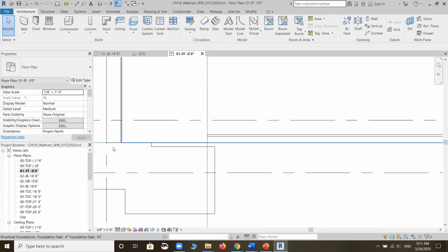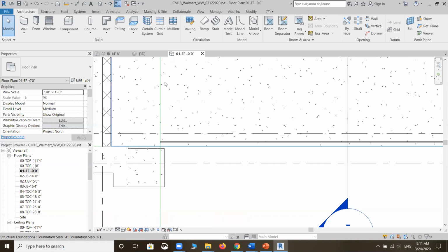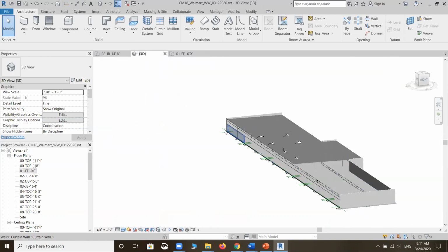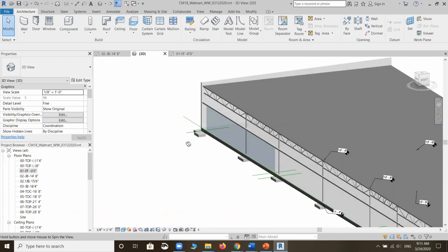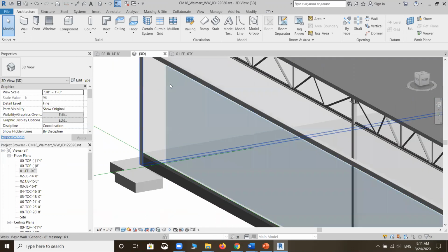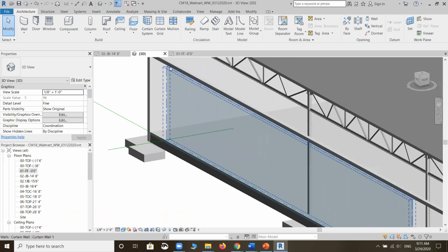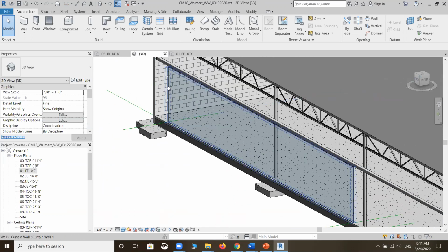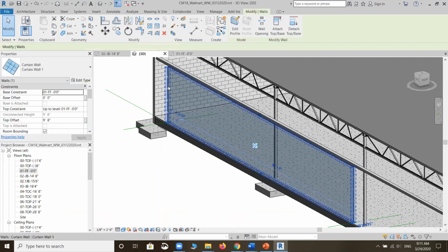Now, you would replace the first section of a curtain wall. What does it look like? So you go to your 3D view and you look at this giant piece of glass. You say, well, it really doesn't look like a curtain wall yet. Well, that's correct, because currently all you have done so far is place a piece of glass. The piece of glass is not the whole thing. You have to put all the other curtain grids in. You have to put the mullions, which are the structural framing system for the curtain wall here.